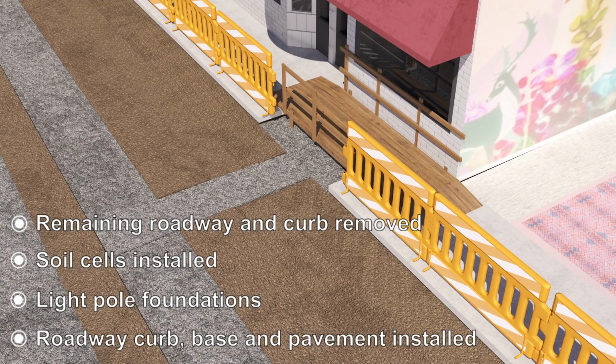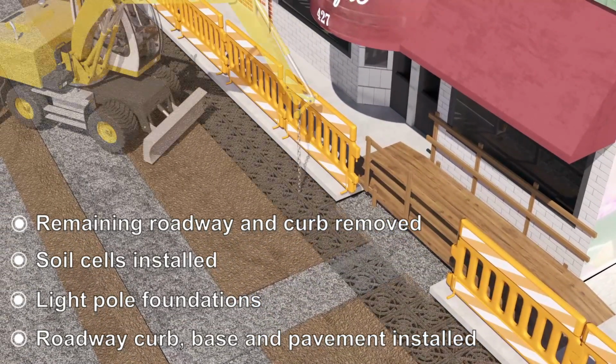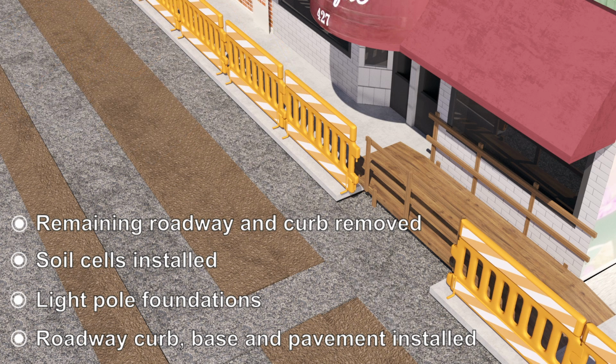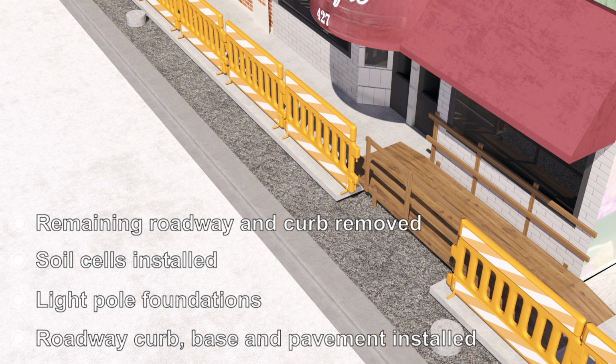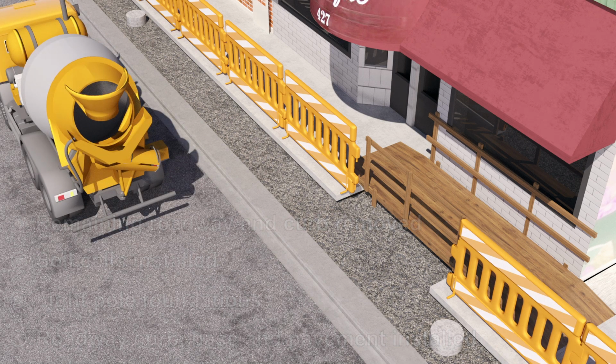Soil cells for the trees are then installed. These provide more room for the tree root systems to flourish. Light pole foundations and irrigation system pipes are installed. New roadway curb is installed. New roadway stone base is installed. New roadway asphalt base course is installed. At this point, the roadway infrastructure is complete.